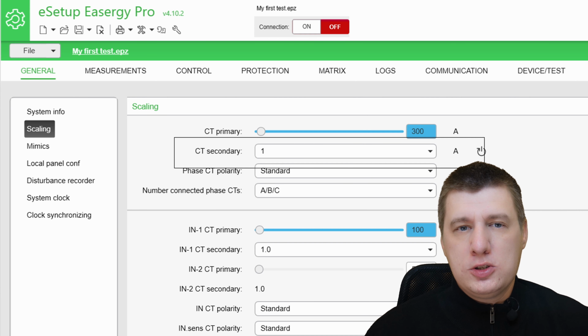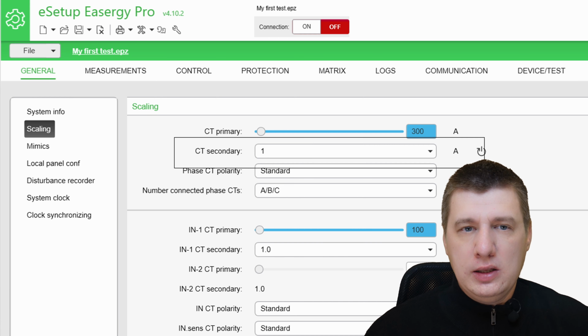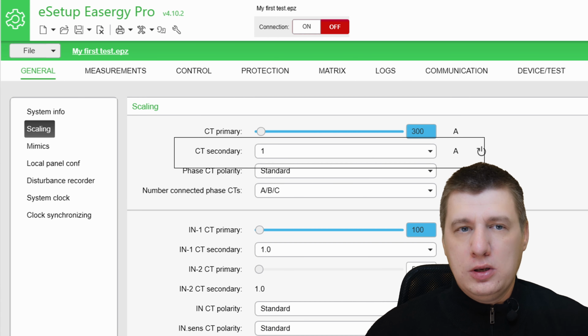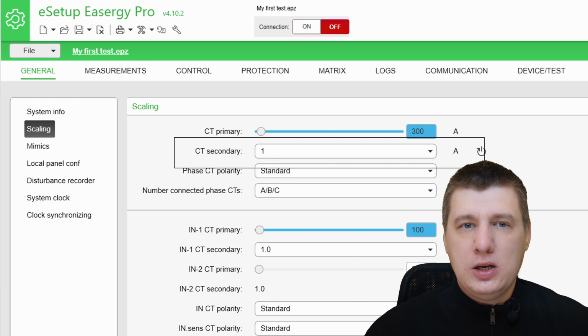You must never open circuit the secondary of live CTs. Doing so produces lethal high voltage and can destroy the installation. The secondary of the line CT must be short circuited before opening any connections to it during maintenance. And do not energize the primary circuits until the secondary scaling settings are properly configured in the relay, as this could cause unexpected operation and damage.